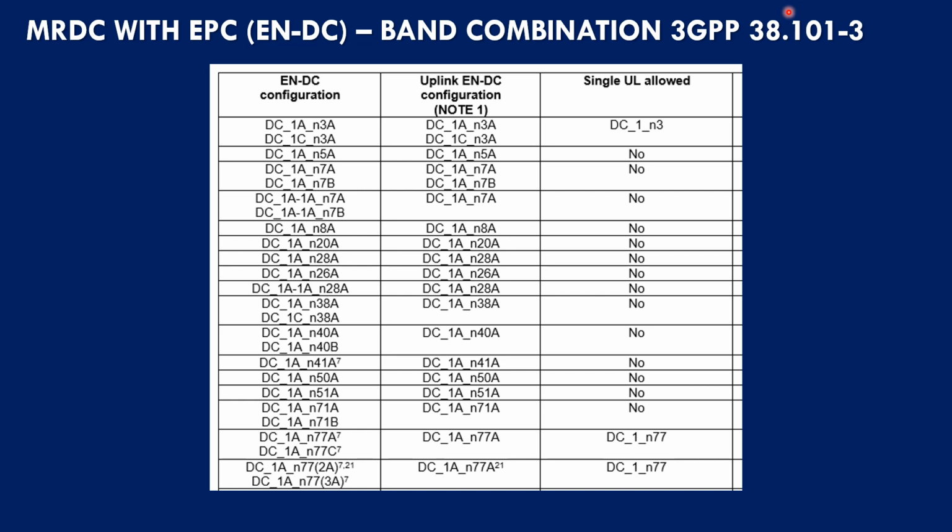In the case of ENDC or NEDC configurations listed in the tables, like we have seen in the example of ENDC, the intermodulation product caused by dual uplink operation may fall into the receive band, meaning the uplink band, where there may be interference due to intermodulation, but there is no interference in the downlink channel bandwidth.